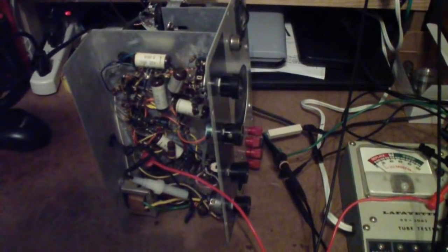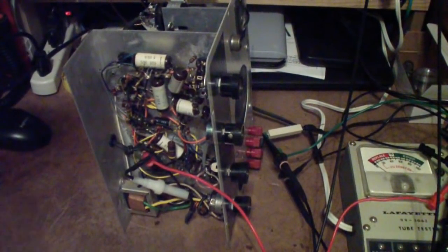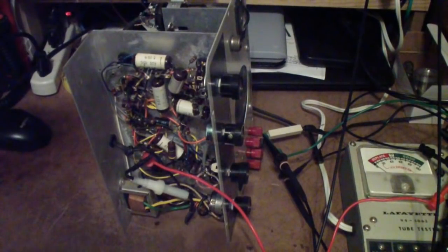The reason I picked that isn't because of any characteristics of the signal tracer, but it just happens to have a 6V6 output stage, so I borrowed the tube, and it has the power transformer necessary to operate that tube, and it includes 2 windings that we can use in a circuit that I'll show you in a minute. So the basic idea of what we're trying to do here is I was trying to see whether it was feasible to do XY displays of the characteristics of 2 vacuum tubes at the same time so that you can match them.